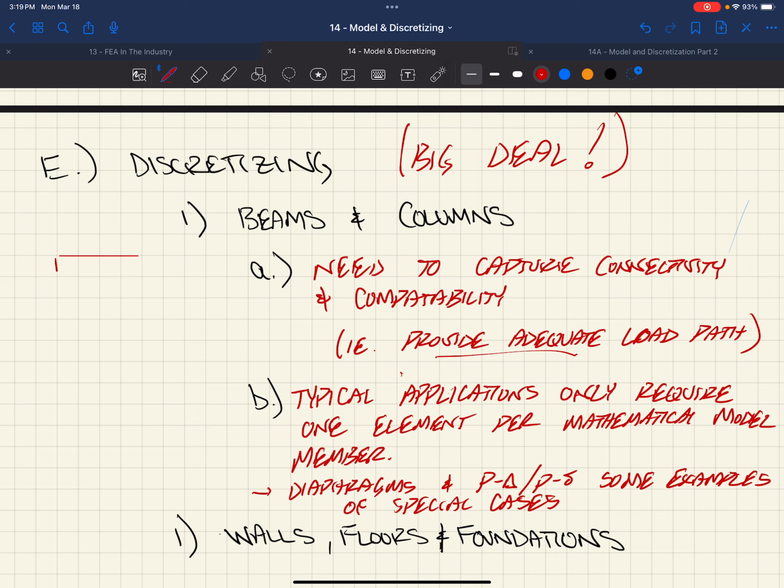We'll make it a special steel plate shear wall. So in a special steel plate shear wall, we end up with beams and columns that bound a steel plate, right? So we've all seen concrete shear walls before, maybe masonry shear walls, wood shear walls, right? It's just some sort of thin in-plane element that carries the shear, right? So steel plate shear walls, special steel plate shear walls are the same thing.